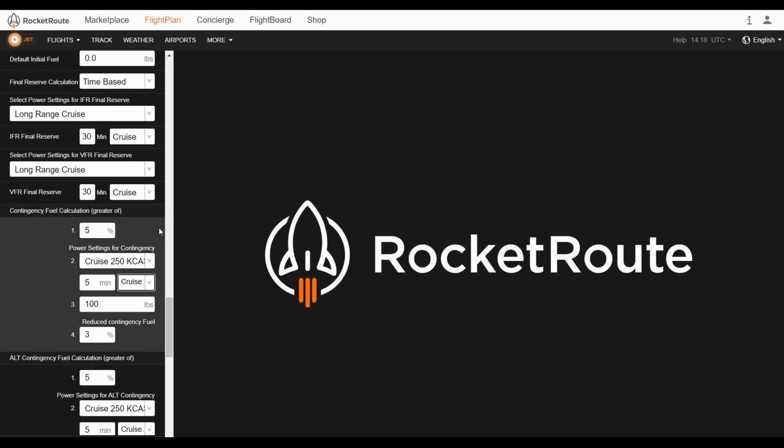repeat it. You can set either the percentage value for contingency fuel or a certain amount of minutes using a certain power profile at cruise or 1500 feet. And also we can just define the amount of fuel as one value. And our system will use the greater of these three settings.